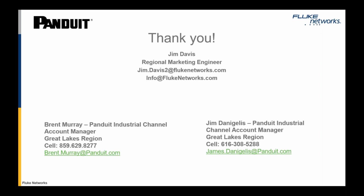And that's where it makes the most sense to go to a stranded cable. You're going to have to derate that cable for performance, but you also need that flexibility, right? You can't have a fishing rod out there in your cable, right? So it's a functional evaluation in using it in the patching applications or the point-to-point connections. If it's a permanent installation, it's always a good idea to go solid core.